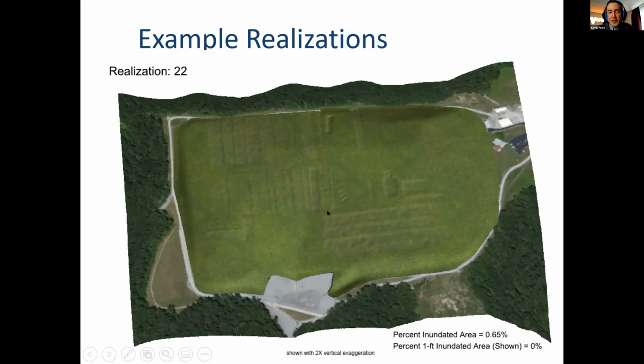We are expecting a certain amount of settlement. You can see that expressed at the surface as these depressions. There's quite a bit of vertical exaggeration on here to get those shadows to turn up, but that's what we're trying to see. The other thing we're looking for is you can see that where these depressions occur, it's irregular. There's little craters and depressions in it that is a result of this random waste disposal, random occurrence of collapsing containers.